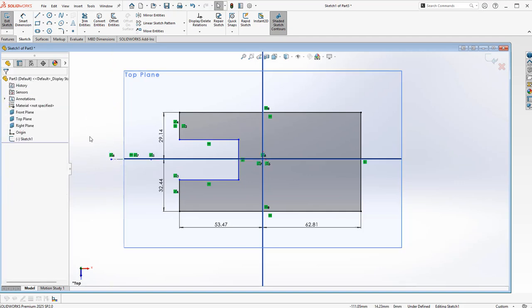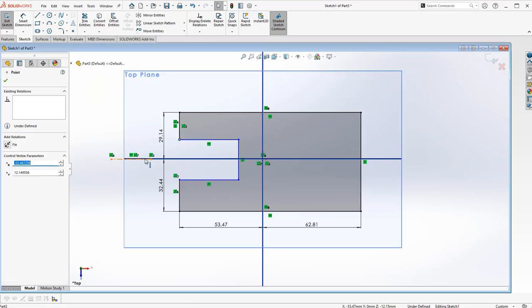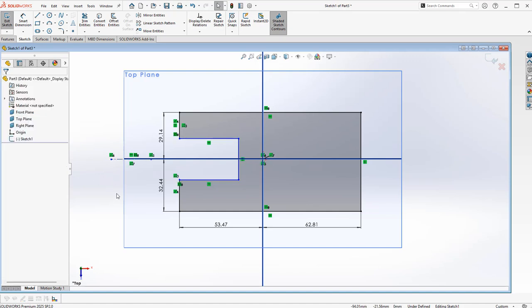I tend to build my center lines off the page a little bit, so I'm a little bit more mindful that that's what I'm in fact grabbing. I'll hold the control key down to establish the vertices, and then symmetry unveils itself.